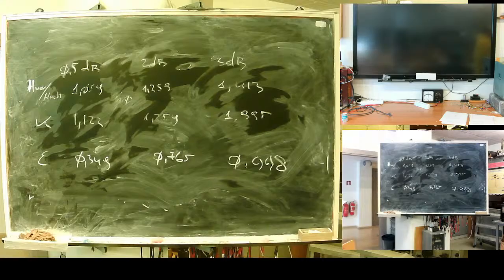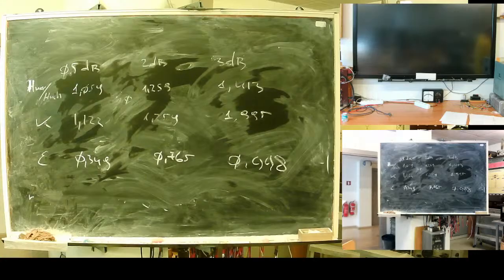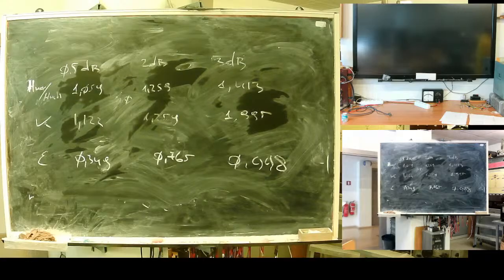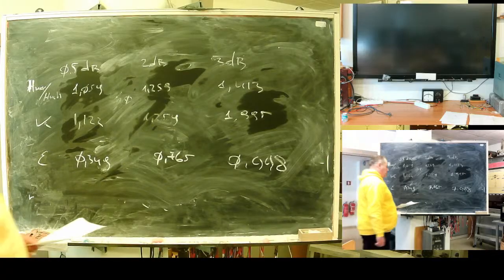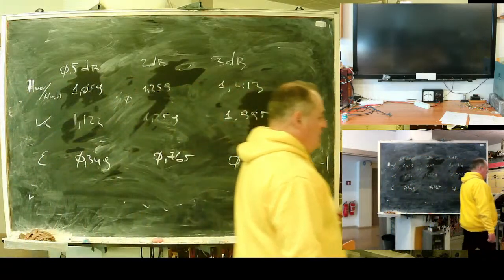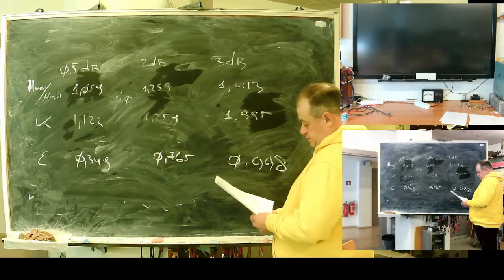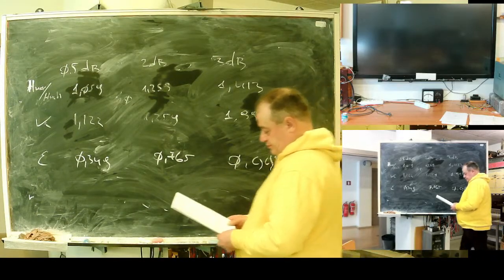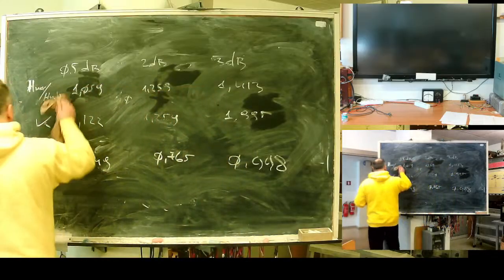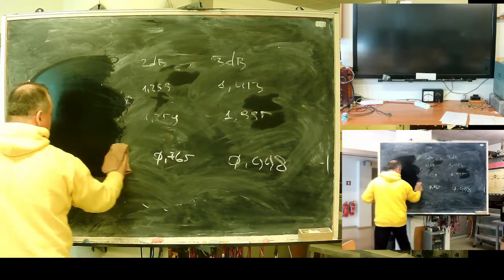For practical purposes, Chebyshev's coefficients are derived from Butterworth. It's easier not to calculate them directly, but obtain them as a derivative from known Butterworth factors.